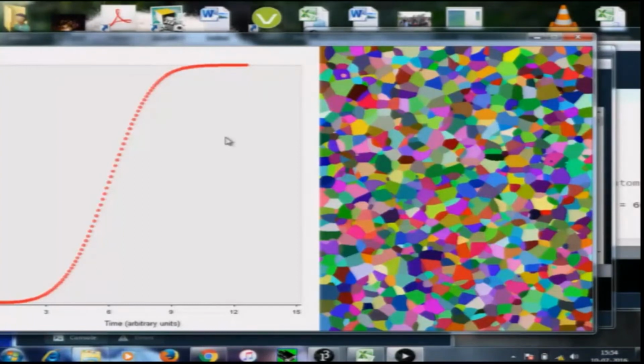So, what happened in this simulation was you had nuclei getting created at a certain rate, and then they would grow at a constant rate in all directions. So, you had isotropic growth, and of course, wherever 2 nuclei would impinge, the growth would stop over there, and finally you get this polycrystalline grain structure that you can see.